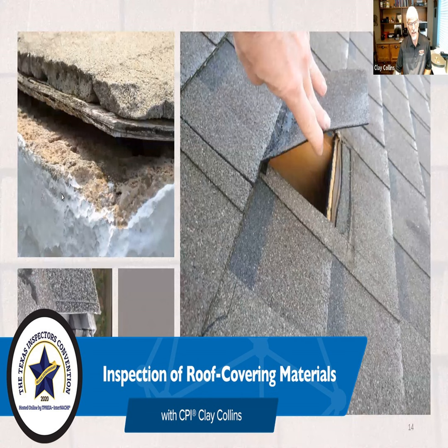So you have the decking that flexes and moves with humidity and heat, and that nail over time will work its way back up, and it will lift that shingle, or down here it will work its way through the shingle. Here it lifted the shingle, and this is at the end cap of a ridge, and they just didn't caulk those. They didn't seal those. I said caulk, but the sealant, which can be a roof grade caulk.